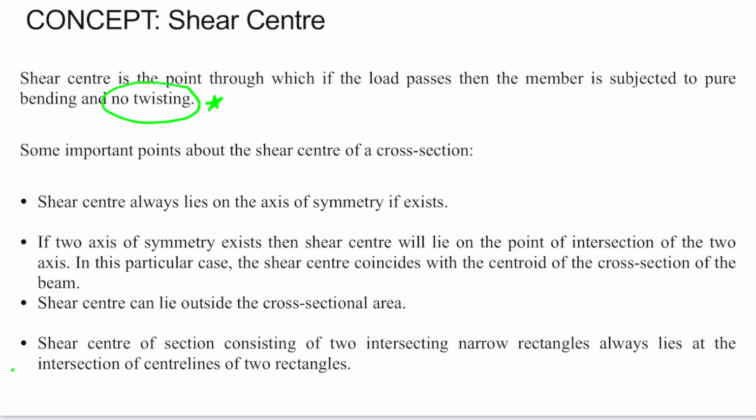A few important points regarding shear center are: shear center always lies on the axis of symmetry, if one exists. Suppose there is a T section, it has one axis of symmetry. So this is the axis of symmetry for the T section. So according to this point, the shear center always lies on the axis of symmetry.